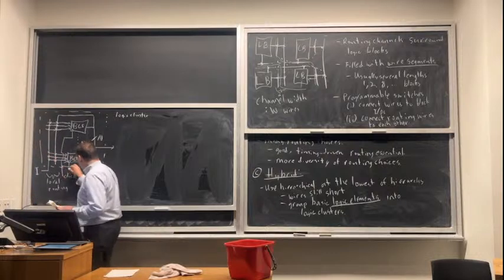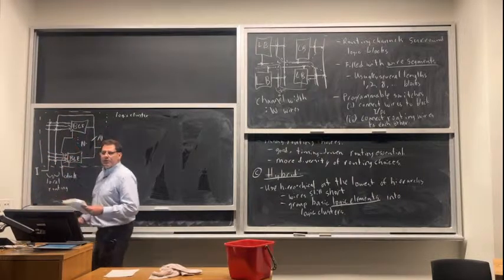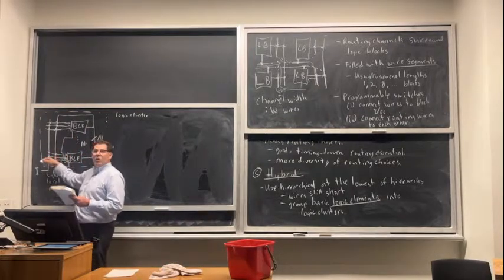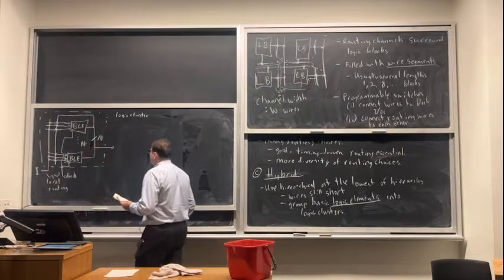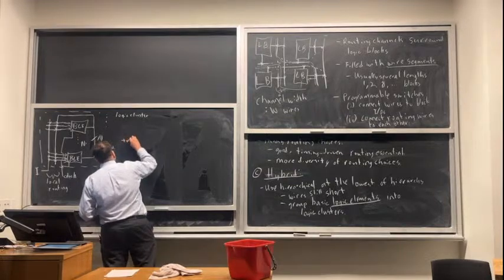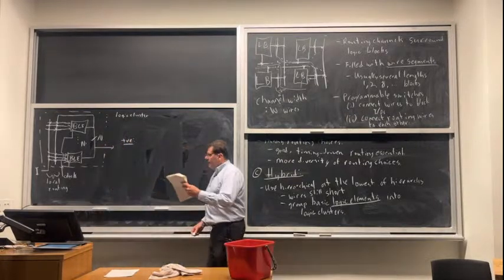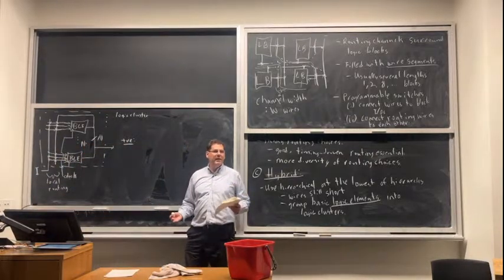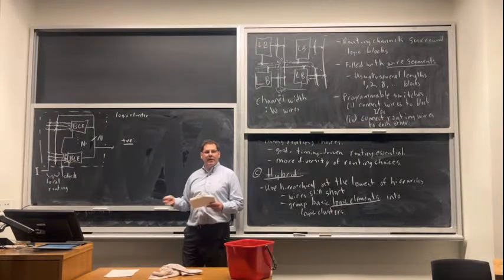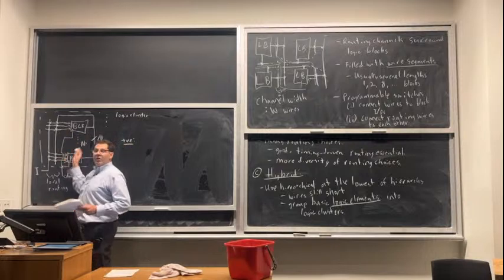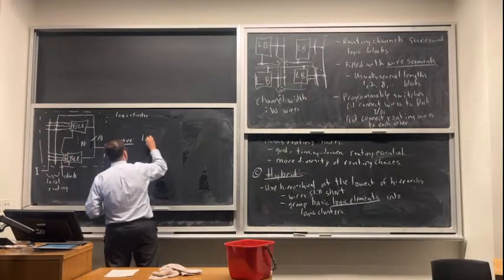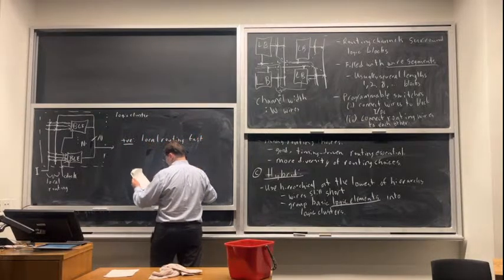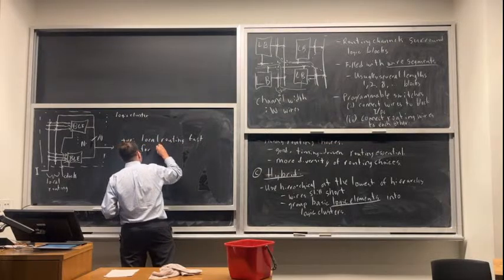Okay, so we've got a clock input here, which goes to all the inputs of each of these BLEs, rather than going into this local routing and using a whole bunch of programmable switches, which would cost more area. Okay, so that's what this looks like. So what are some positives? The positive is that this local routing is actually quite fast as long as you don't make the cluster too big. So it's typically faster than the island-style routing for this small hierarchical FPGA. Okay, so local routing is fast for small to medium clusters.